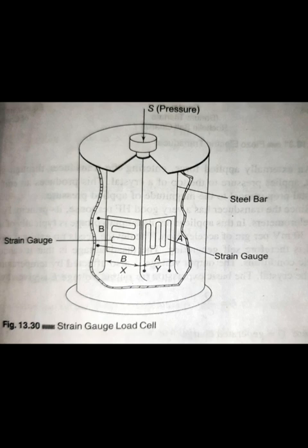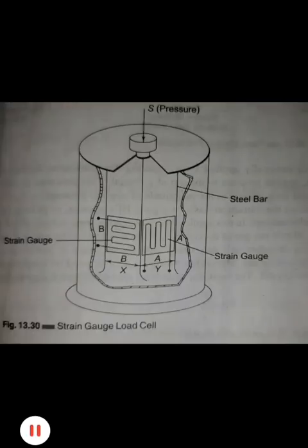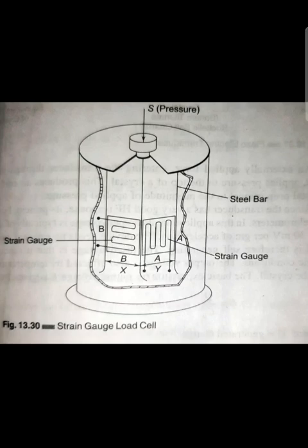The strain gauge is attached to a flexible backing, enabling it to be easily applied to load cells. This allows the minute changes to be measured. Since the change in resistance measured by a single strain gauge is extremely small, it is difficult to accurately measure these changes.